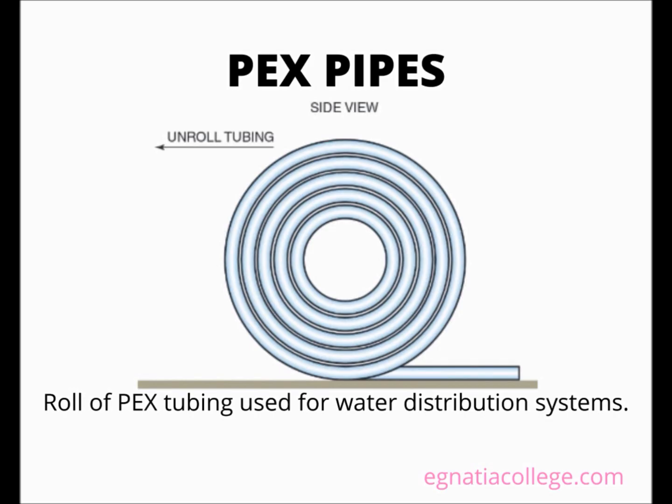As with all flexible tubing, PEX will kink if the radius created is too sharp. The flexibility of this product also indicates that it must be supported at closer intervals than is required for pipe. PEX is shipped from the manufacturer with a UV protective cover. Long-term exposure to UV rays will damage the integrity of the product.